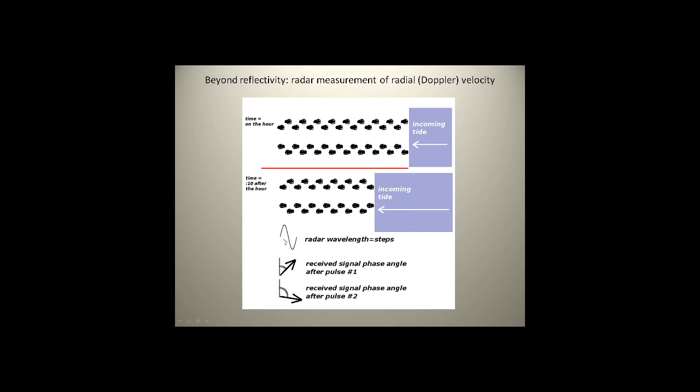And in the same way, we just want to know how much of a wavelength the distance to our target changed by between pulses. And it's easier to make that measurement with the radar by considering the phase of the signal that comes back. So a full wavelength of the radar is a complete cycle. That's 360 degrees. You're going around and repeating the same thing after 360 degrees. So if we compare the signal that comes back to a stable reference that we make, we can measure this phase angle that comes back from each signal reflection from the target. This is the same way you made your measurement twice, 10 minutes apart. We're measuring this phase angle every 1/1000th of a second.